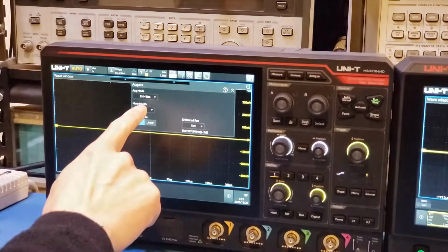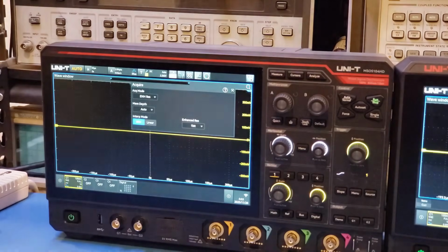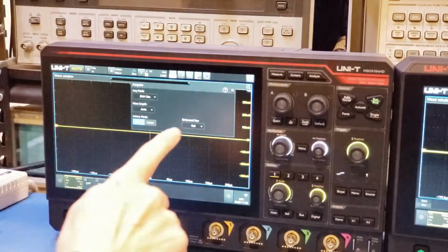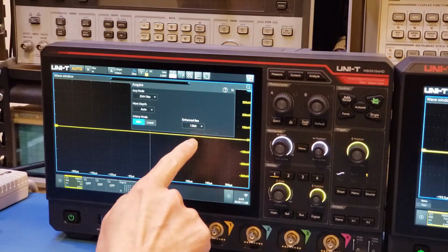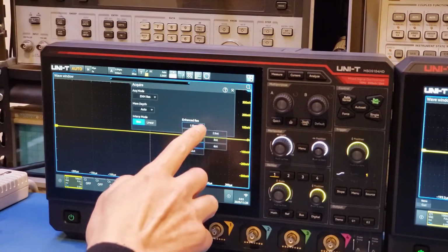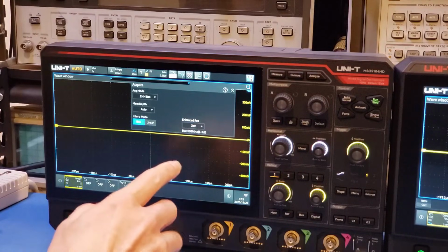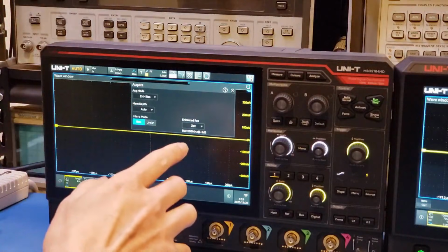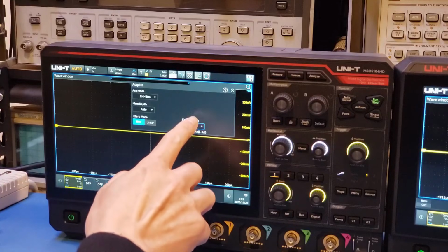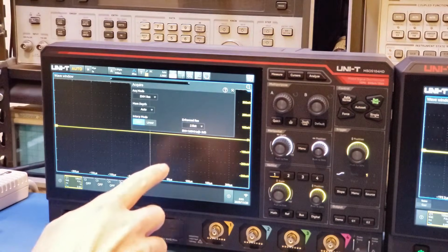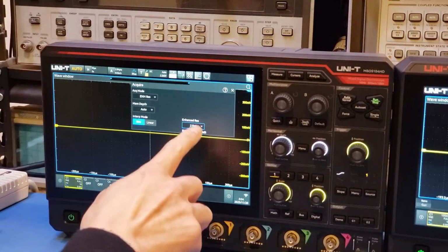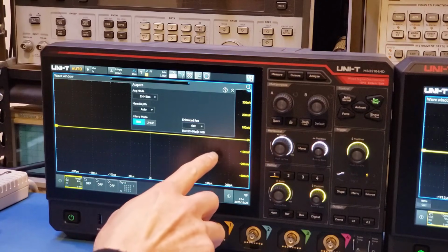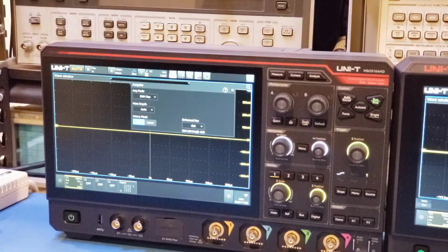So let's leave the memory depth as auto, and let's take a look. For 1 enhanced bit, you can see that we don't lose any bandwidth. And let's increase it to 1.5. And we don't lose any bandwidth either. So let's change it to 2 bits. And now you can see the bandwidth immediately is limited to 500 MHz. And as I increase the number of bits, you will see that the bandwidth drops even further. So for 2.5 bits, you can see the bandwidth dropped to 160 MHz. And for 3 bits, it drops further to 62.5 MHz. And for 4 bits, now the bandwidth is only at 25 MHz.